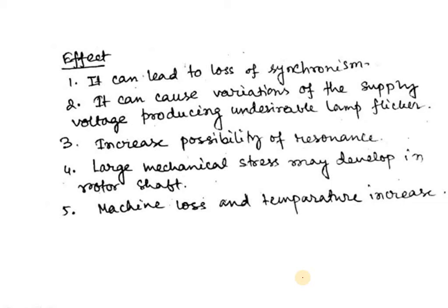Thirdly, increased possibility of resonance. And fourthly, large mechanical stress may be developed in the rotor shaft. Definitely, if the rotor starts oscillating and tries to achieve a new equilibrium, more torque is produced. So definitely mechanical stress will occur in the rotor shaft.